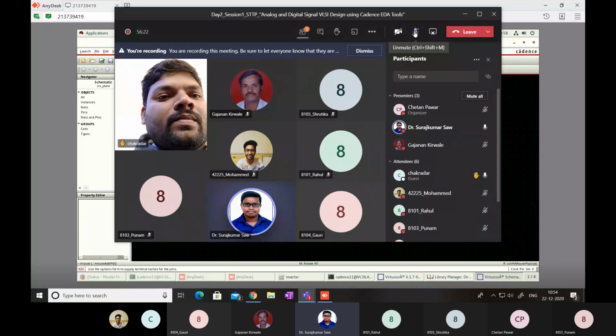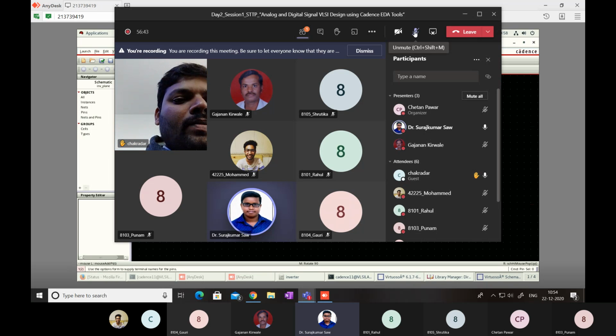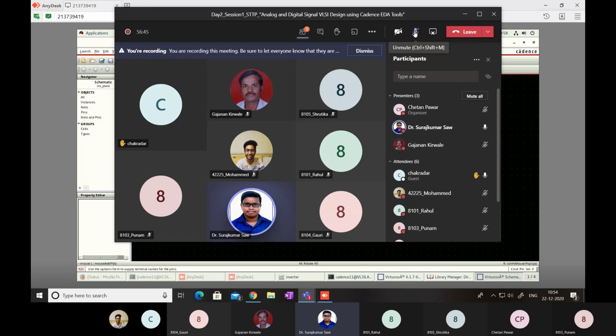You just provide different input, right? And for you also, you have to input A and B. Just make it enable and provide different values. Let's say first we provide pulse input only. You just need to change the period. Period we have already defined as 100 nanosecond. In one you put 100 nanosecond, in another you can put 150 nanosecond, whatever you want. Just put some different value.